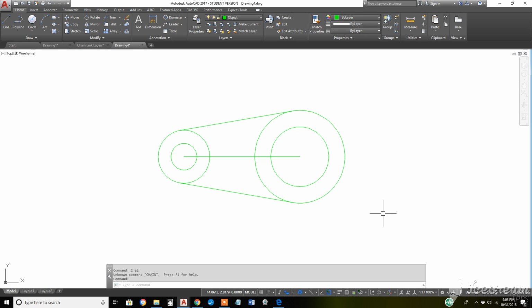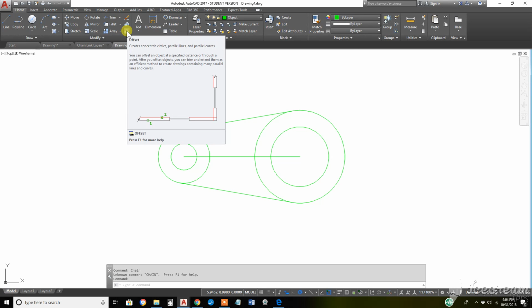That last video ended a little sooner than I expected, so we're about to offset these two diagonal lines. Again, the gray move icon in the middle of the screen is the watermark of the Icecream free version I'm using, so disregard it. The offset command is this lower right icon in the Modify panel of the Home tab.